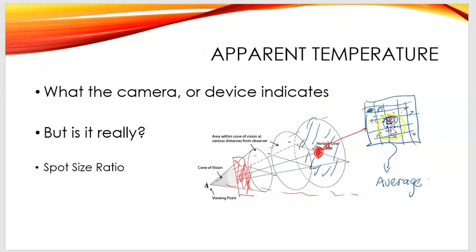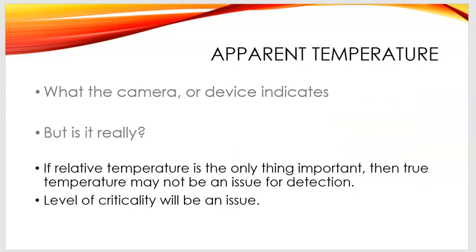If you're too far away, you can see the hot object in the camera. The hot object will show up, but if it's got that averaging temperature like most of them do, it won't be the accurate temperature, but you will be able to notice that there is a hot object in there. So yes, it's good, but don't totally trust the temperature it's telling you if there's a lot of background temperature also being seen by the camera.